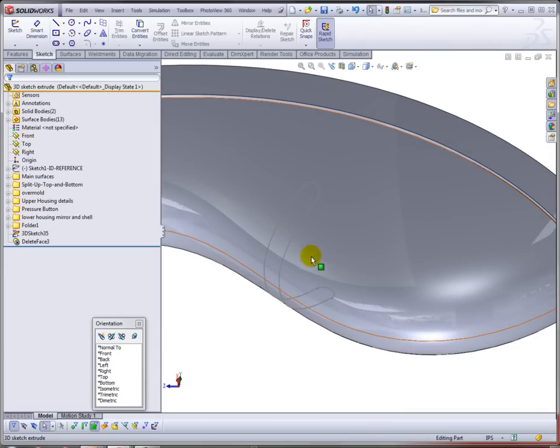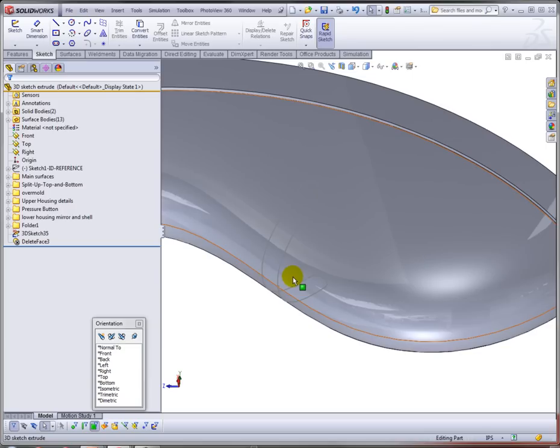And you can do that in SolidWorks with 3D sketches. Before I do that, though, I really need a direction. That's one additional piece of information that extruding a 3D sketch needs, because 2D sketches know their direction based on the plane they're drawn on. A 3D sketch doesn't necessarily have a sketch plane that it's built on.